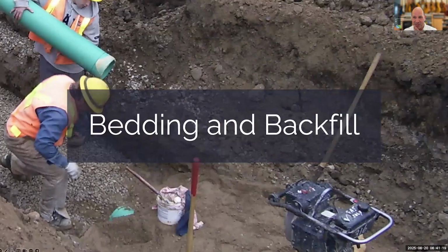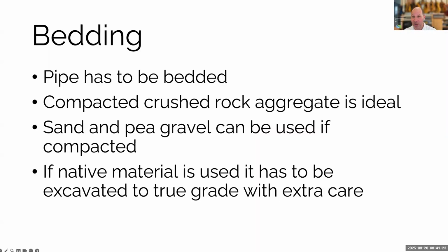So let's talk a little bit about specifics of bedding and backfill, right? So rule number one is pipe has to be bedded. There are certain circumstances where it's installed without bedding, but you have to be really, really careful. So typically, the idea is that you'll dig a trench, they'll put specific bedding material at the bottom, use that to dial in the slope, compact it, and then install the pipe and compact around it. Typically, compacted crushed rock aggregate is what's going to be used, assuming it's available.